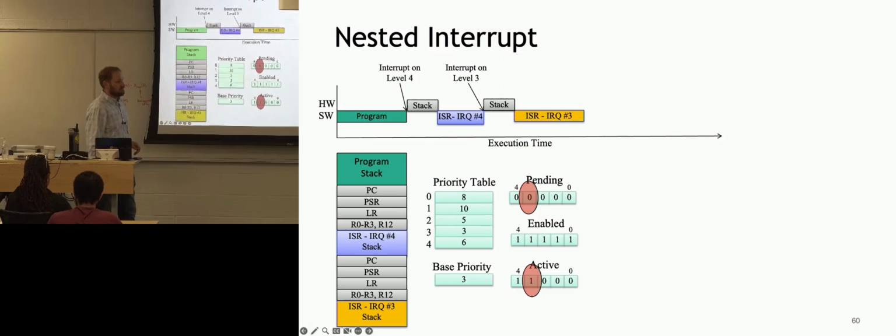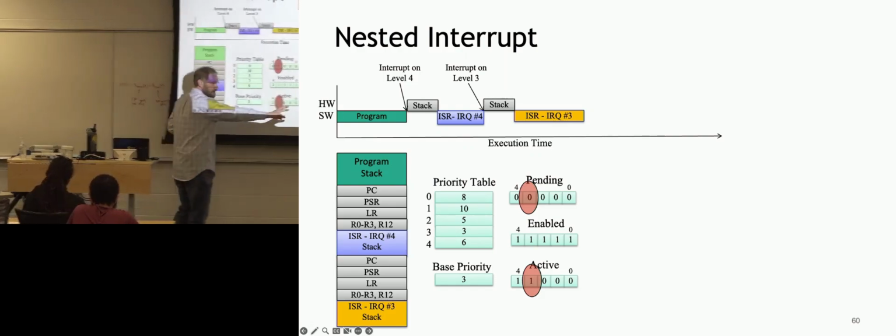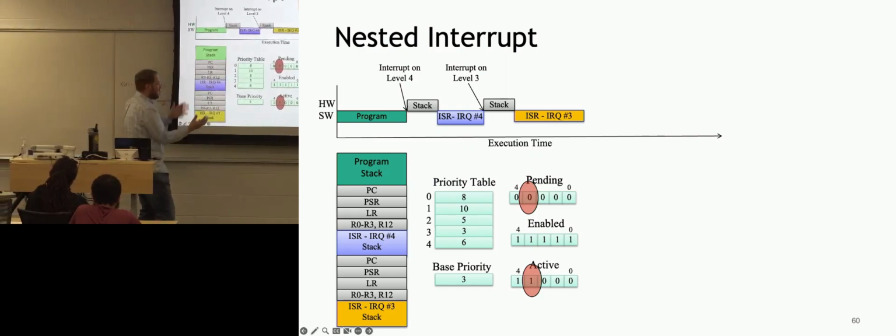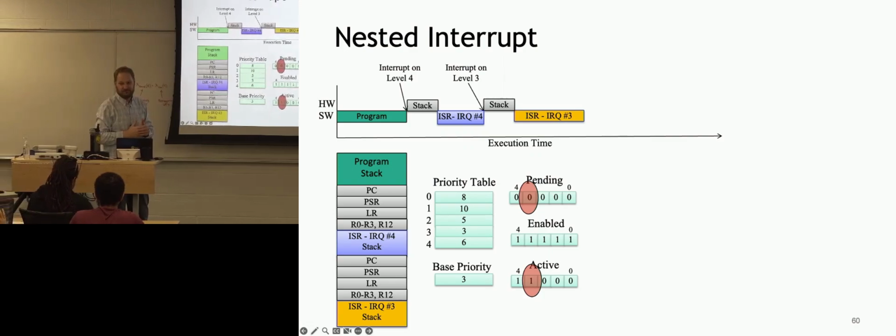So that's like hardware deciding that, or hardware knowing that. Well, the hardware is dumb, as dumb as hardware can be. It says, I get a BXLR to FFFFFFF6. I take whatever's in the stack and put it in the core. It just happens to be that the information in the stack represented the action of doing IRQ4. And now you're back into IRQ4, and you're going to do it. So the action of unstacking puts you back to where you were. You keep unstacking with a BXLR to FFFFFFF4 until you're back in main. How's that feel? Okay.